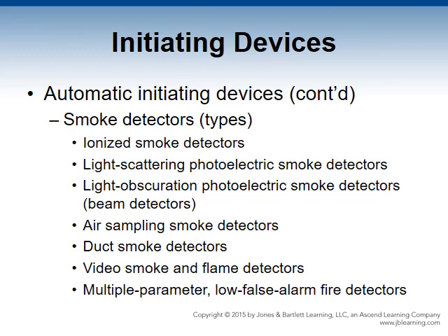The system digitizes and processes multiple sensor readings that are then compared to the chemical indicators of fire. These systems also use MEMS-based particulate sensors and classifier devices to increase chemical measurement reliability. The system protects difficult-to-reach locations such as storage depots, cargo bays, and aircraft.